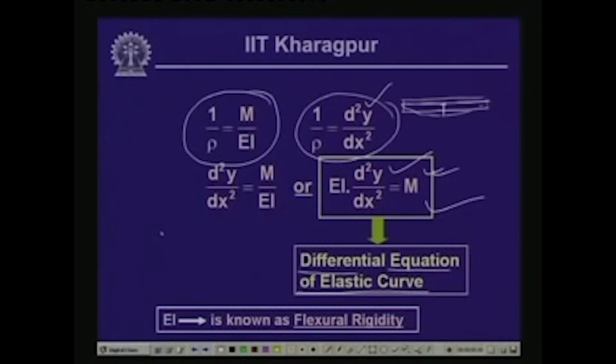as we know, the shear force V equals minus dM dx. Hence, if we take the derivative of this expression, we have EI d3y dx3 equals minus V, and as we know, q equals dV dx, where q is the uniformly distributed load on the beam.